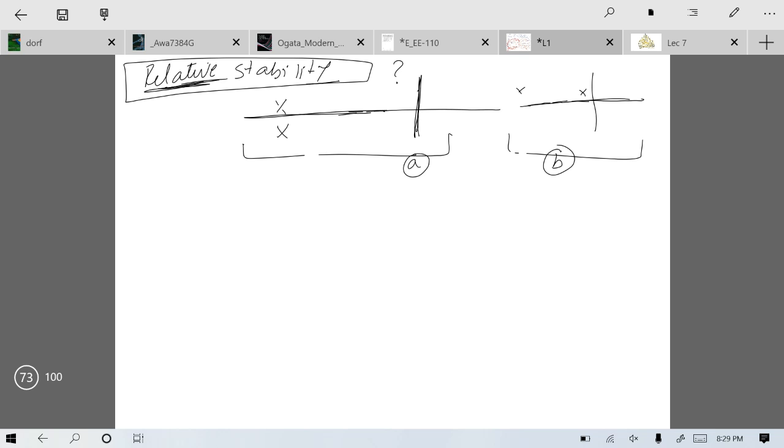However, previously, when you were able to find the roots of the system, you could see from the poles that the farther the pole, the greater margin you have to reach the right half plane. So, the farther the pole, the more stable is your system. If your poles are over here and you have some variables that affect the location of your poles, then you have a large margin to reach the right half plane, so your system will not become unstable easily. However, in the other case, one of the poles is already on the boundary, and if any variable changes the location of this pole, it has the tendency to move to the right half plane. So this B is less stable than A.